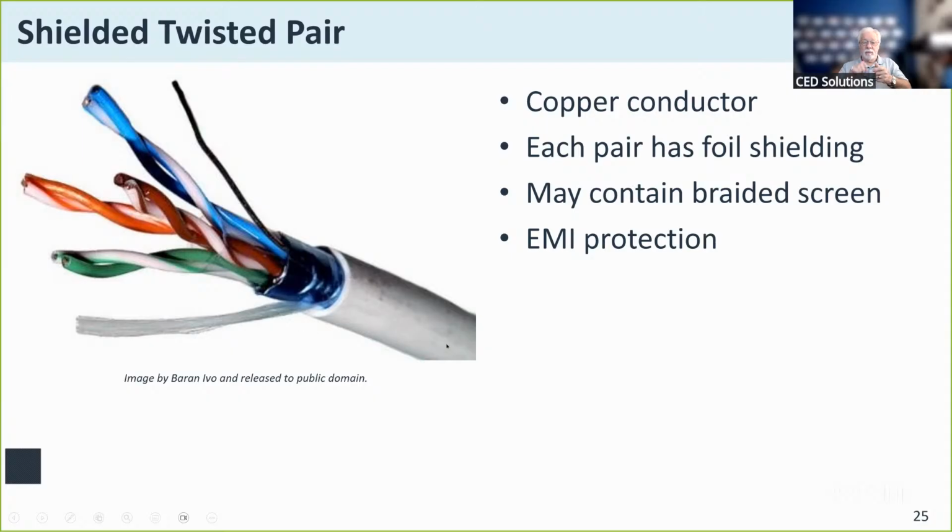Instead of using a razor to try to trim back the casing on this, where you always cut into the underlying wire, if you just put a little bitty slice right there in that casing and then use that fiber, you strip that sucker down to wherever you want it to go without cutting in and providing ground-out possibilities on any of the other wire.